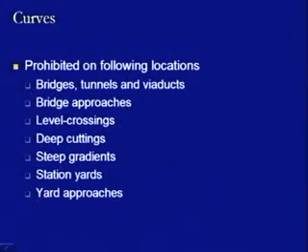In the case of level crossings also, if a curve is provided, it will increase the length of the track on the level crossing section, and this is another hazardous condition. It has safety implications, because the persons crossing the railway track have to move longer distances and remain for more time on the railway track. So, this is not good for their safety.